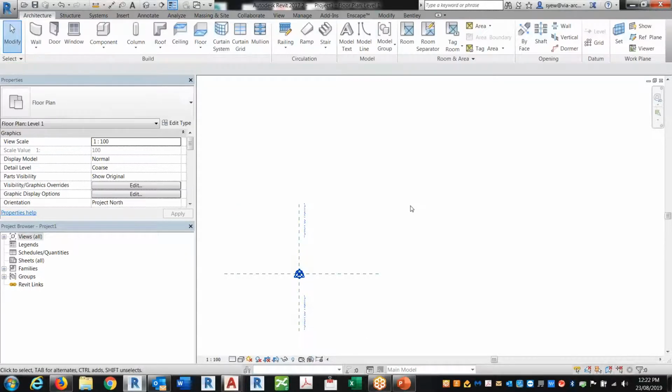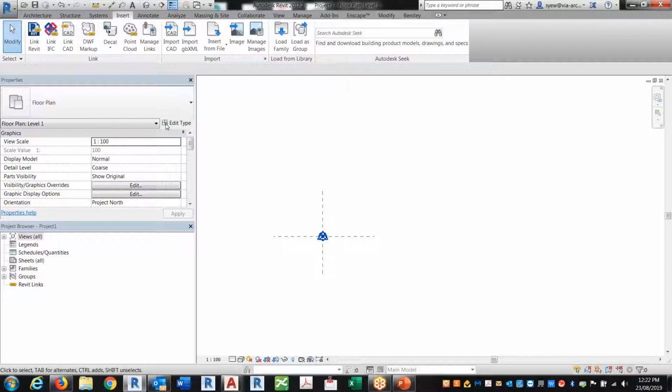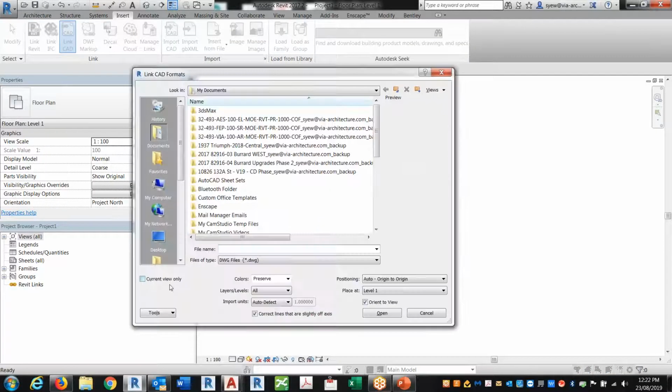Okay. Now the next thing you want to do is insert a file. Oh no, not a Revit file, an AutoCAD file that you're going to be using for, let's say, your shared coordinates. So the first thing I would do is go Revit link. Okay. I'll go current view for now. Now the origin point, I always set it to auto center to center, preserve, I always turn this off. This one I would just go meters.